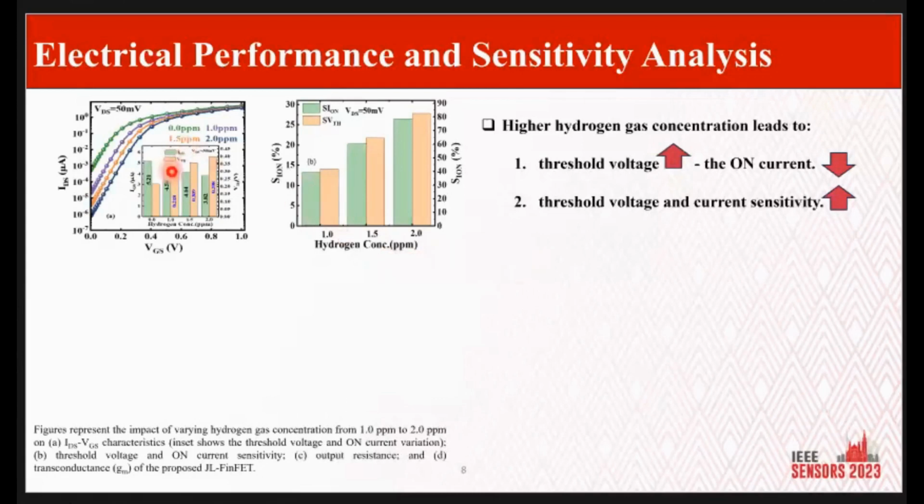So it's in the bars and it moves from something which is around, I don't know, 0.2 to something which is 0.4. So you have an increase of the voltage threshold. When you talk about transistors and memories, there are four so-called figures of merit: I off, I on current, subthreshold slope, and this voltage threshold.